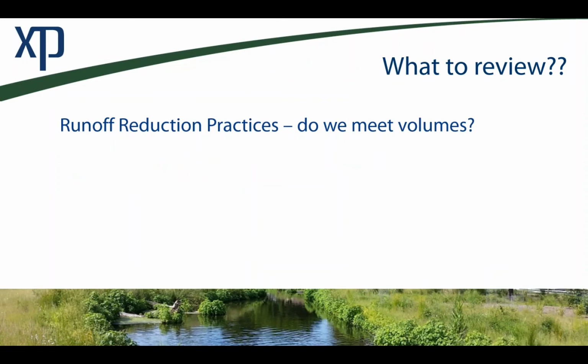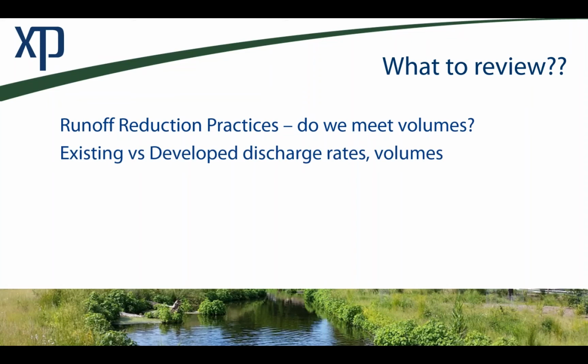I'd say the very first thing, often the start of our design process, is to meet the water quality guidelines. How do we treat the water quality on our site? That's often performed by runoff reduction practices. So does the volume that we need to treat with runoff reduction, is that being treated? Beyond just the runoff reduction, that water quality event is something we're going to start with knowing and understanding.